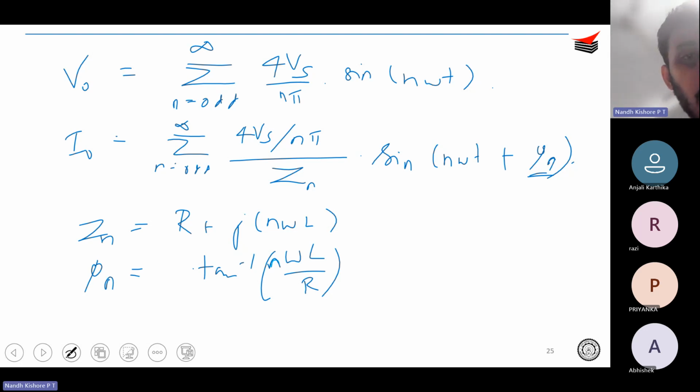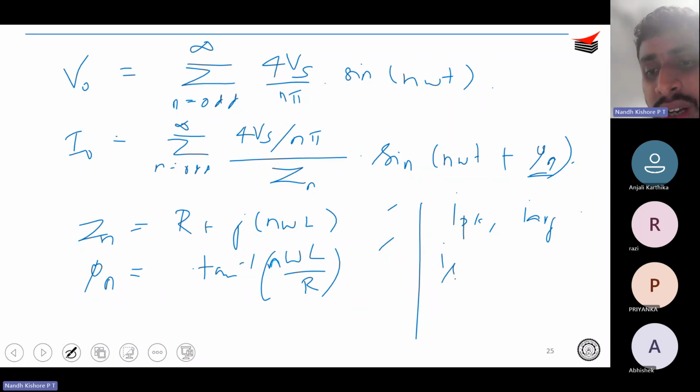So in this also we saw problems: calculate the third order harmonic, first fundamental, fifth order and so on, or calculate the most dominant harmonic for single phase or three phase. It will vary based on that. Calculate the harmonic power corresponding to the third harmonic. And we also saw problems on what is the peak switch current, average switch current, and of course what is the source current. Or for how much time the diode will conduct, how much time the switch will conduct. So these are some things that we saw.